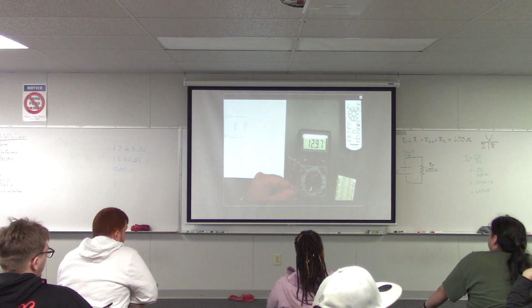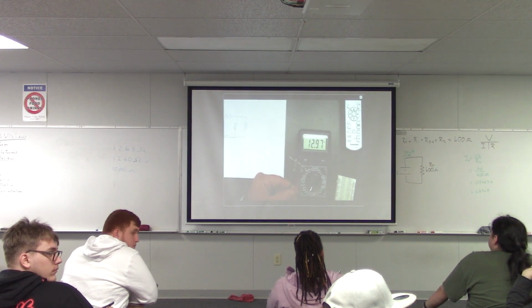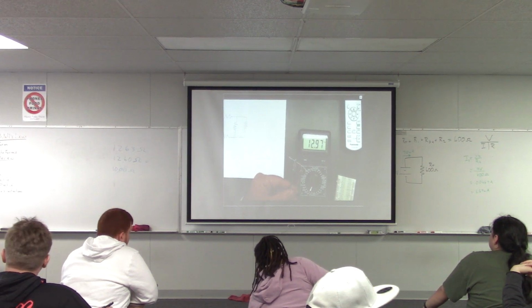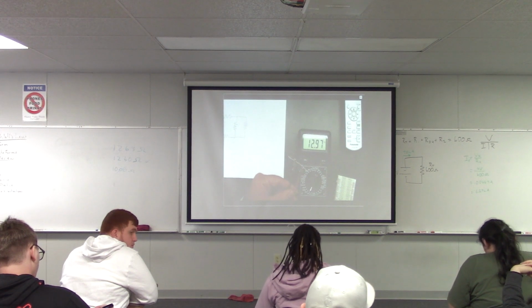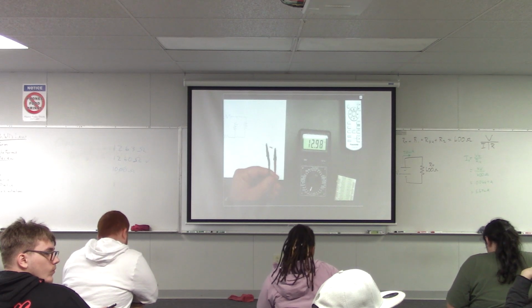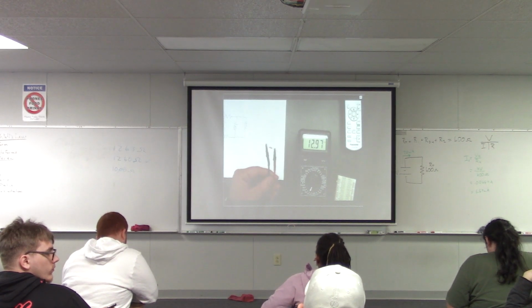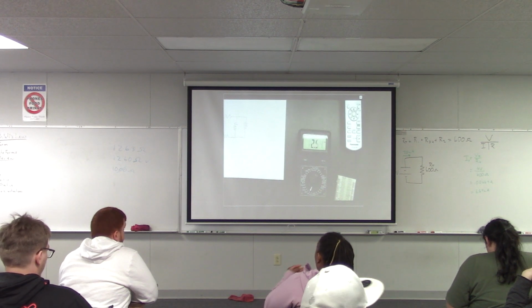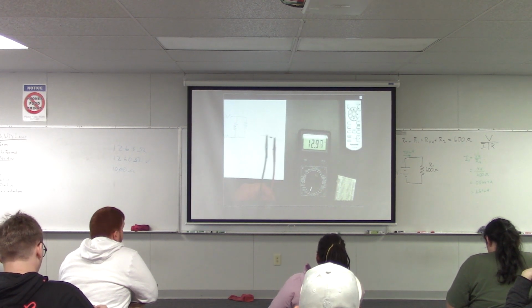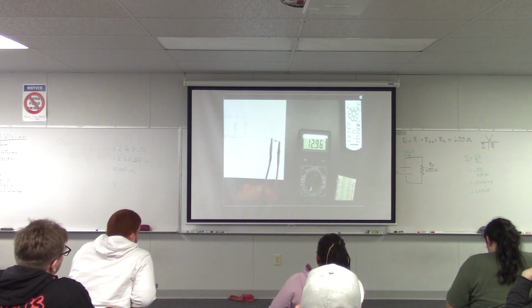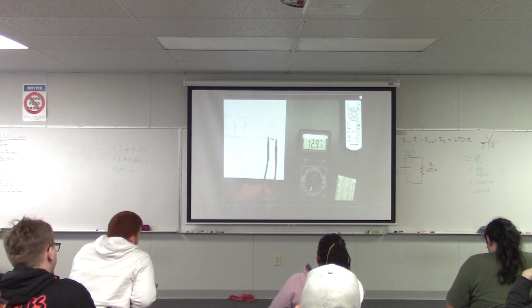In my classroom, I began having problems with the clip leads, where they go into the meter. They've been bent enough. They used like a number 40 wire in some of those new ones. Oh boy. And they have been intermittent. You look at it, it'll be 12.97K. You move it a little bit, and it may be 3 point something K. So you might want to check those leads if you start having problems, because they should be steady like Jordan has them. But yeah, I've had that quite a few times. I had to have them replaced.